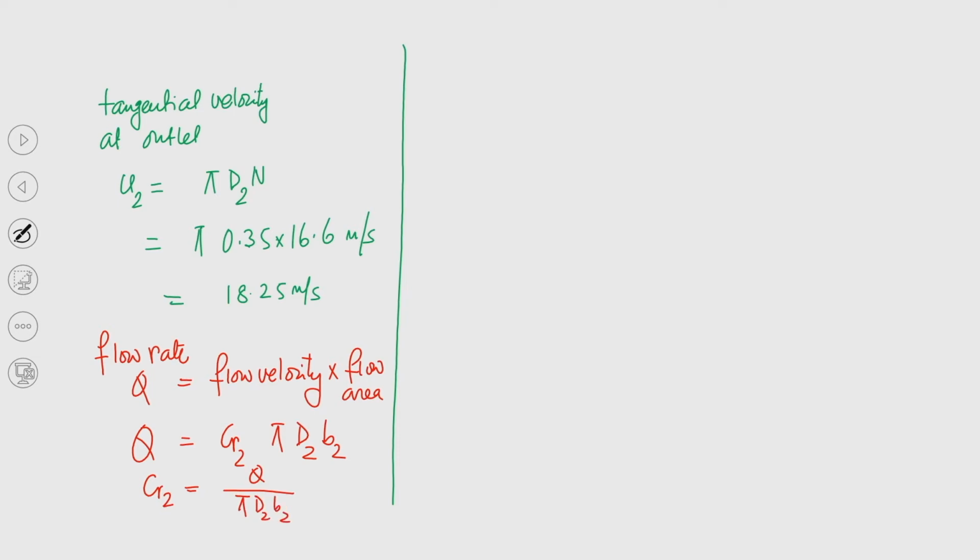Now, as I said, this is the total flow area, but this is not available for the flow. What is available is 95%. So, we have to multiply that area by 0.95, right. This is the flow area, but 5% of that area is occupied by the blades. So, naturally 95% we are getting for the actual flow, and that is why it is multiplied with 0.95.